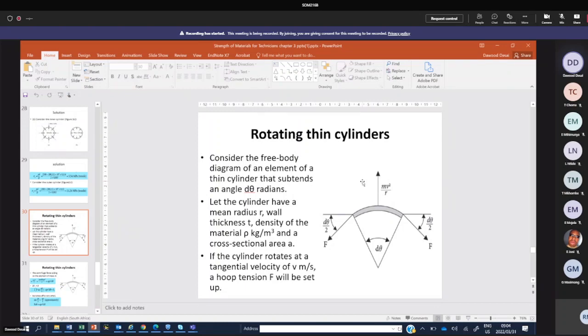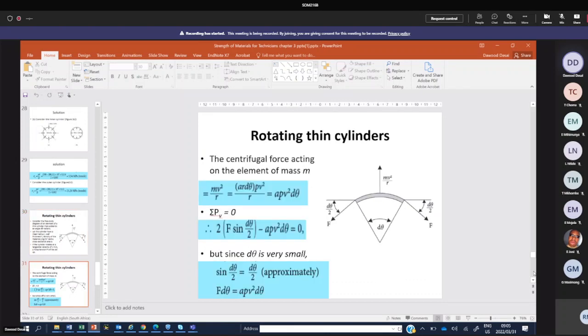All right, now what happens? Nothing major. You got a normal cylinder under pressure, so you use the theory I already taught you. Now if something is rotating, what force comes into play? Centrifugal force. So you just add the centrifugal part also, and then you calculate the total stress. Okay, so you can see it's mv square upon radius over here. Density is rho, kg per meter cube. Tangential velocity is in meters per second. You can see why mechanics is important. All right, so they're just deriving the formula here for you.